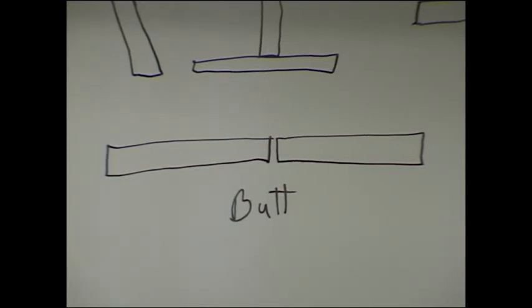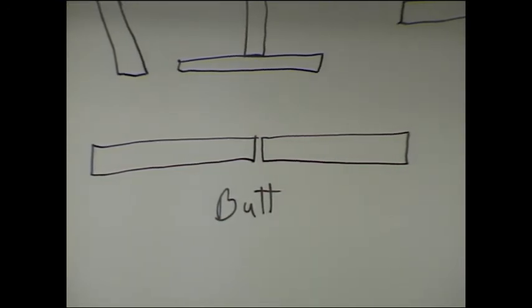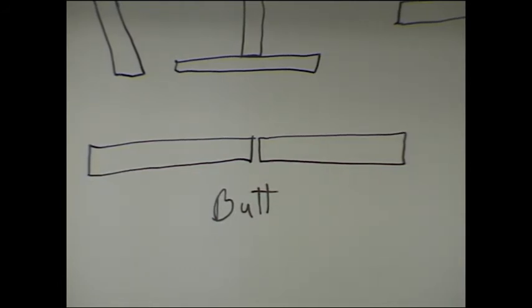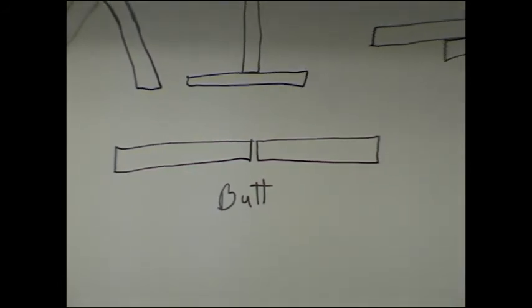When you're welding a butt joint like that, you should always make sure that the joint crack stays in the center of the molten puddle, center of the bead, and the plate edges are completely fused, and the penetration must extend through the root, which means that as you're welding along, you want to pop a little hole in between the joint edges. This is called a keyhole, and it'll open up and it'll round out, and that gives you an indication that your edges are breaking down and fusing completely, and that you're pushing filler metal through to the back side. And once again, the reinforcement, in other words, the cover on the back side, should not exceed more than about 1/16 of an inch above the surface of the base metal.